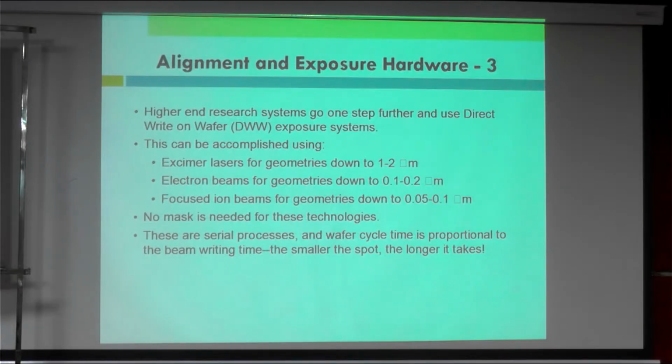Higher-end research systems go one step further and use direct write on wafer exposure systems. This can be accomplished using a laser, with a geometry of 1 to 2 micrometers, electron beams for geometries down to 0.1 to 0.2 micrometers, and focused ion beam for geometries down to 0.05 to 0.1 micrometers. In this case, no mask is needed for this technology. You just expose the laser or the beams directly. It's a kind of write directly on the